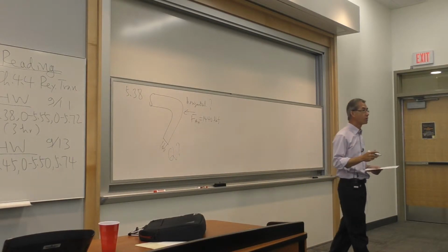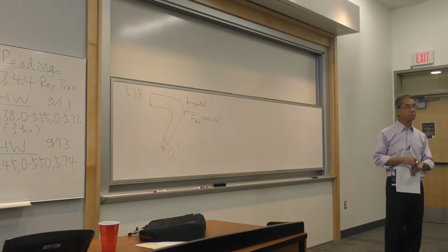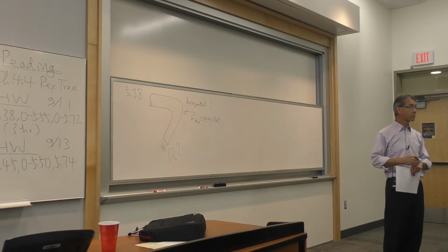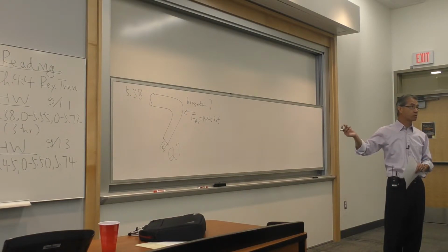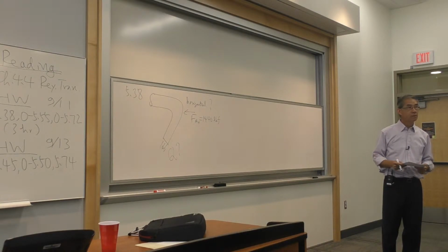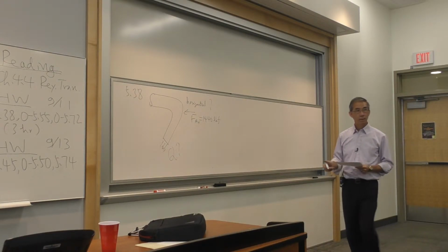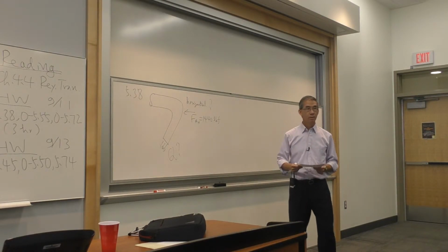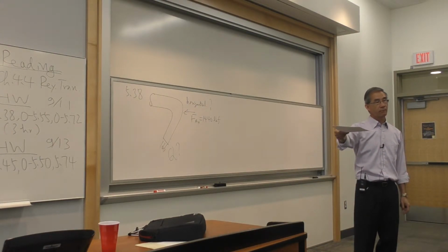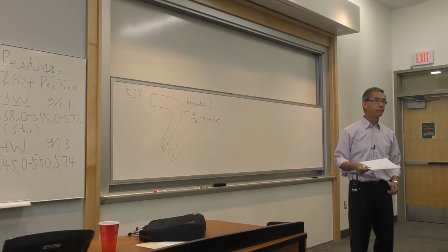Kind of different from the normal problem you have done in the past, where you're given all the velocities, or you can find them from continuity, and you're asked to calculate the anchoring force. So this is just a little twist. Instead of giving you the velocity, I give you the force, and you find the flow rate. Yes? So the top prototype is horizontal, and then it makes a greater than 90-degree turn? No. The whole thing is horizontal, and you make a 45-degree turn. The whole elbow is on the table. Right?